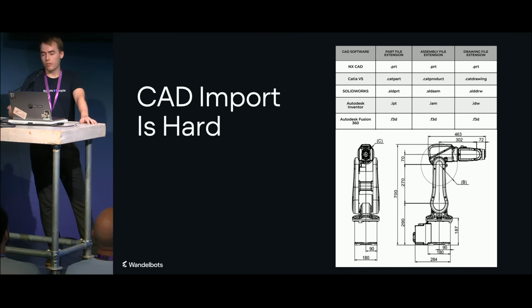We need accurate 3D models, not just for visuals, but to extract something called the Denavit-Hartenberg parameters for each robot. These parameters are the basic mathematical description of a manipulator's kinematics. Manufacturers provide most of the numbers we need in their data sheets, sometimes. So we measure directly from the models just to be sure.